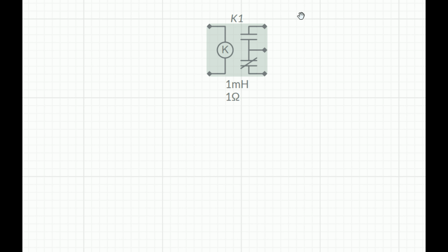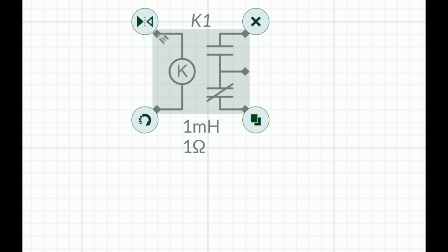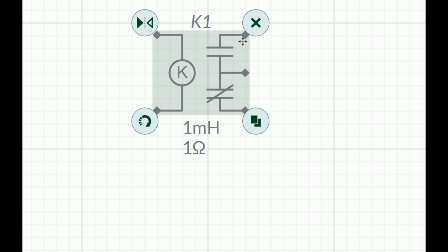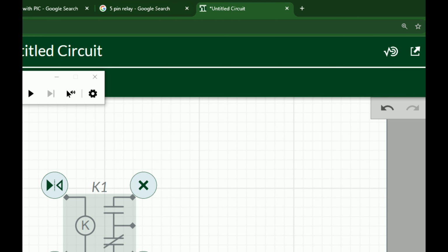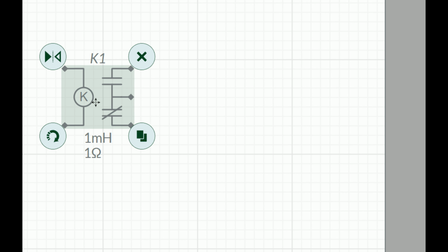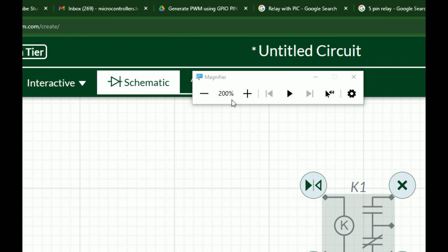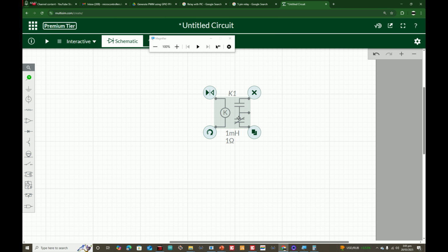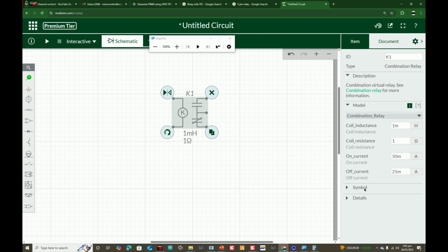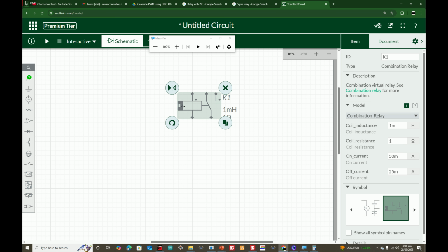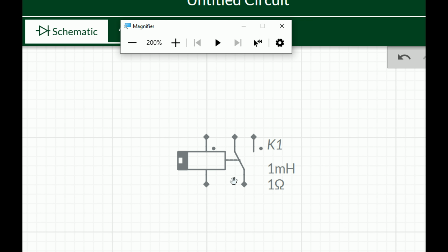Now see over here how many terminals it has. These are coil A, coil B, or you may call them A, B, whatever you want. Then you have a separation, and then you have a common. This is the common, this is normally closed and this is normally open. In other terms, you may draw it as it has multiple symbols. The second symbol that is also available, go to the symbols, this one. It is also clear, sometimes it is shown like this because this is the common port, common, normally open and normally closed.